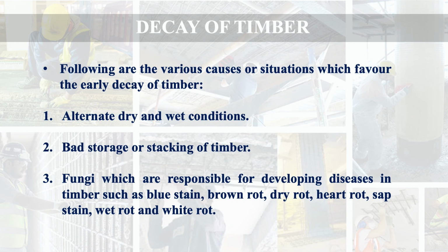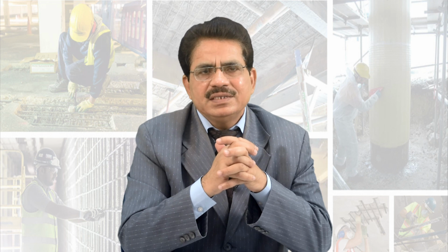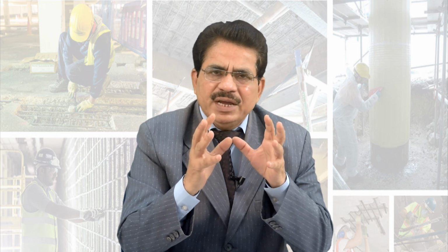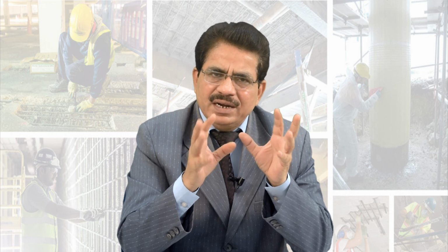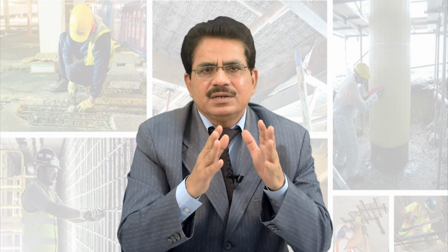Then fungi, which are responsible for developing diseases in timber, such as blue stain, brown rot, dry rot, heart rot, sap stain, wet rot, white rot, etc. Then improper seasoning. If the seasoning is not done properly, then certainly this unseasoned timber will be liable to attack by many fungi, insects and the natural forces also, and it will decay quickly. So proper seasoning of timber is a must for keeping the health of the timber good.